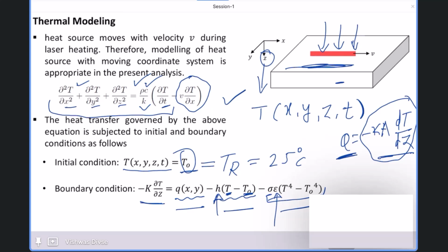Let's say surface heat flux is only applied on the top surface. So we'll select only that top surface for the heat flux. If the convection, let's say you are applying on all 6 surfaces, while applying the film coefficient in Abaqus, select all those 6 surfaces and you will apply convection. So the model will take care of where convection is applied, which surface is insulated, or whether you want to consider radiation or not.